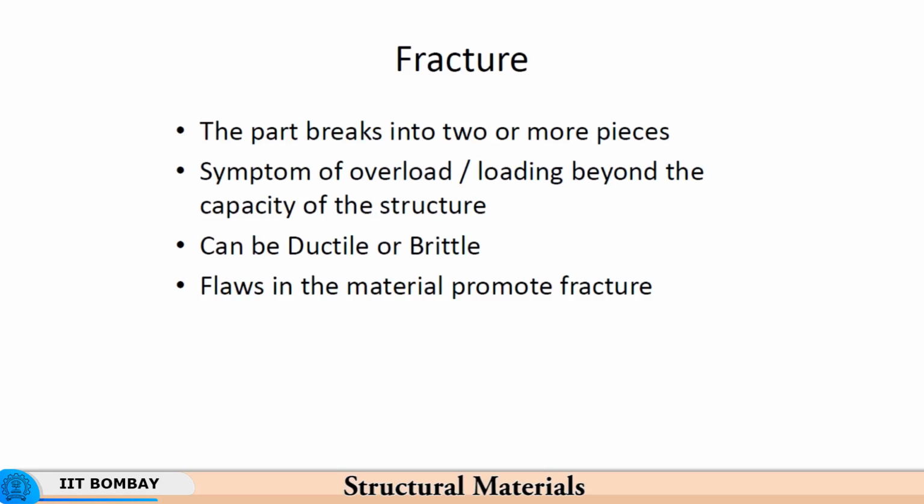So, if you have designed a part to perform a particular function, maybe a bolt or a nut to hold a certain amount of load, a crane hook for supporting a certain amount of load, well, the inability of the hook to support that much load would be treated as failure, but the hook can also fracture, meaning that the hook can split into two pieces under certain circumstances, and therefore break into two. So, the integrity of the structure can be maintained in spite of the structure failing to do its job.